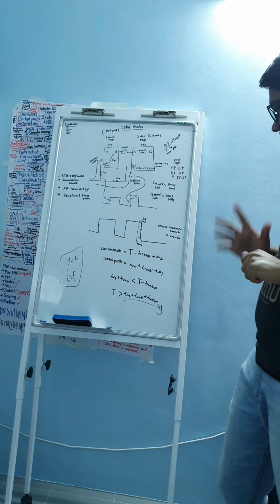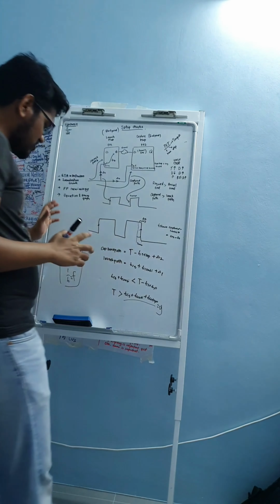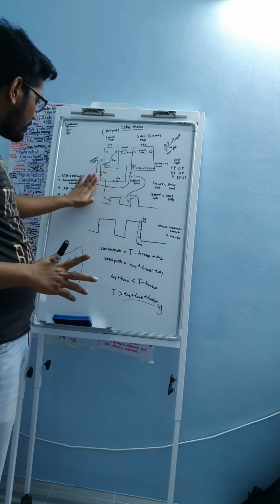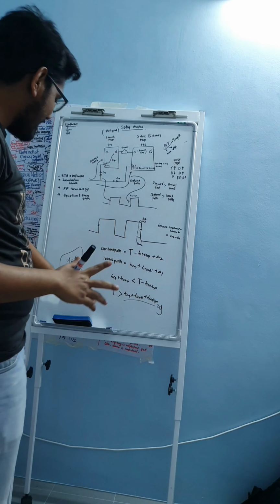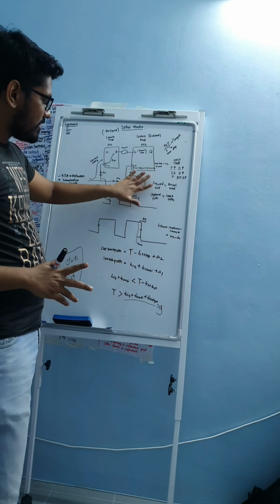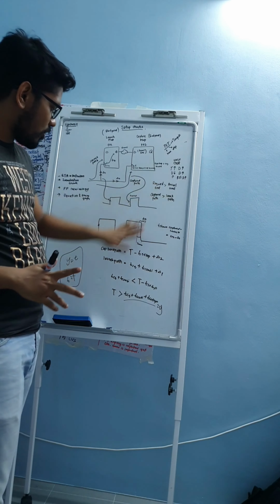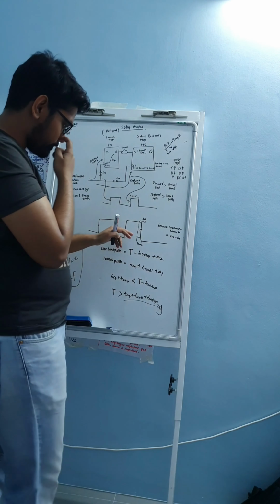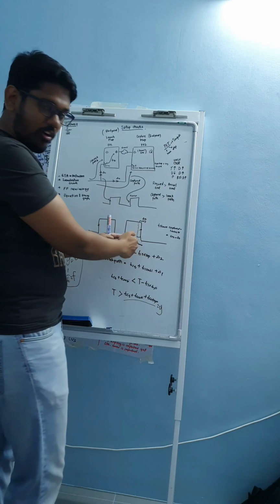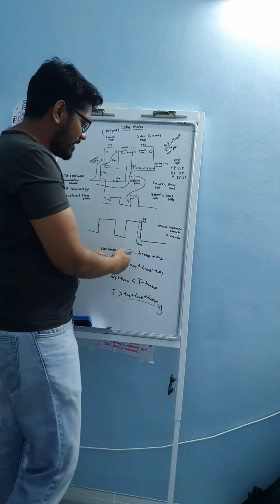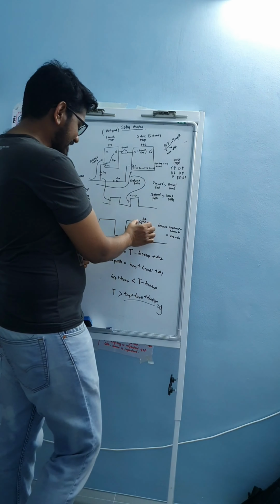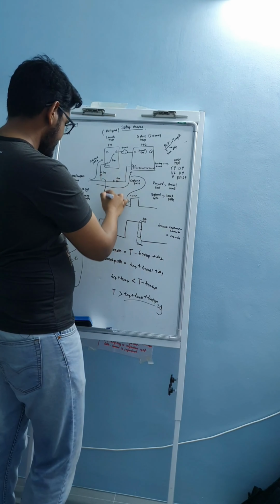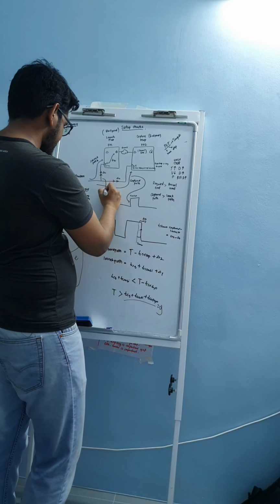I hope I've covered everything over here. We covered how to do a check on frequency. From here onwards, you can do a check on frequency without any delay being added. It will be easier. And then we talked about the formula for required and arrival, captured and launch. And then we talked about the timing diagram, making sure that the data has to arrive before the T setup over here. And if a delay is being introduced, you're going to add a delay over here. And this is a capture part, and this is a launch part, not to forget.